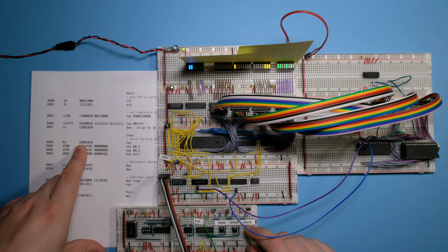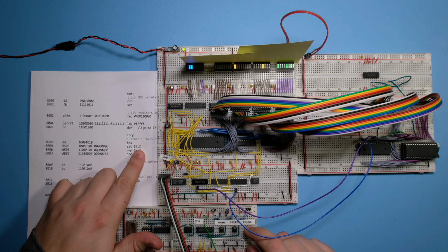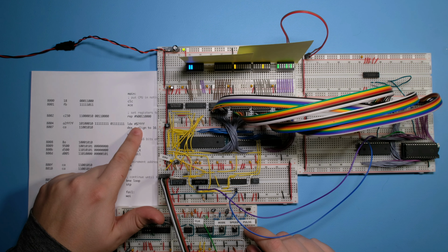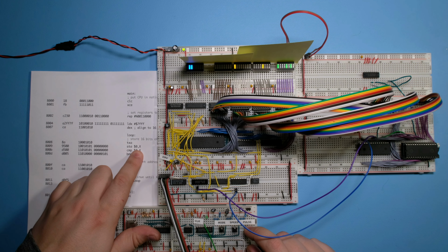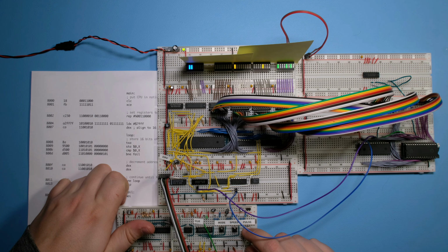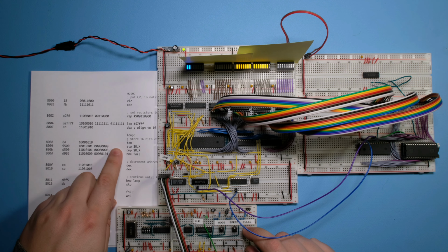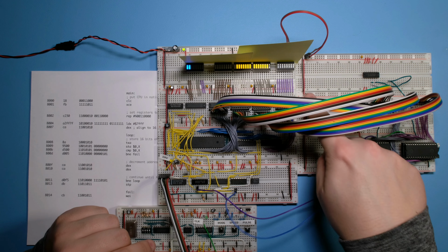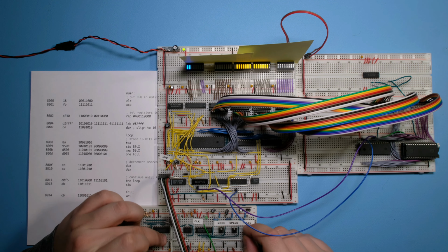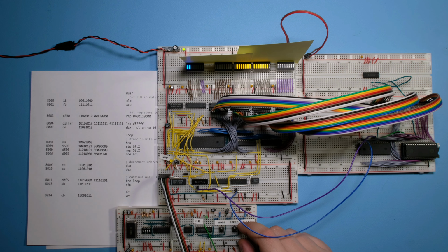So we are going to transfer X to A. Then we're going to store A at the address that is pointed by X. So we are storing at the moment 7FFF at 7FFF. So we will see a write. So we're loading an instruction. And then this is the write. So, okay, at the moment the data is off because this is the low clock cycle, but remember the write is only active, the CPU is only writing data when the clock is high.